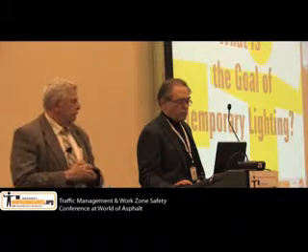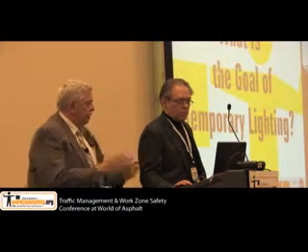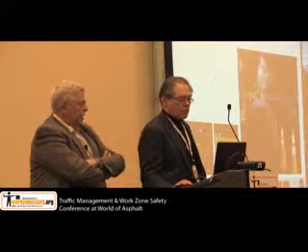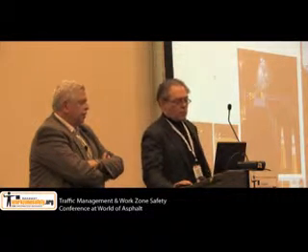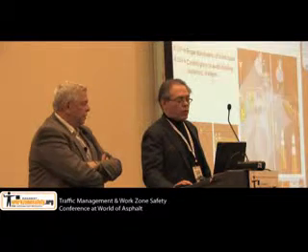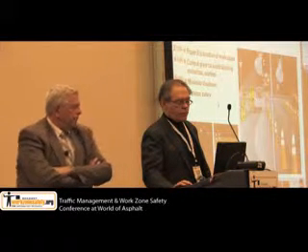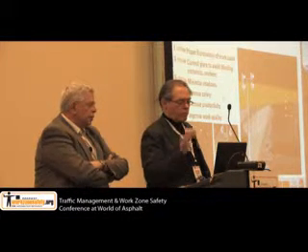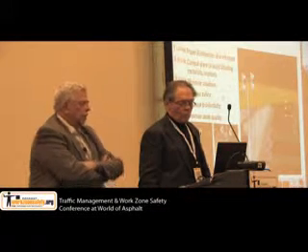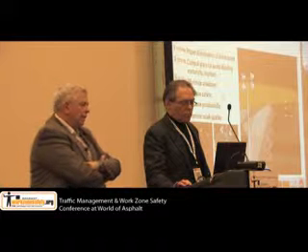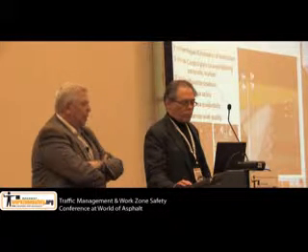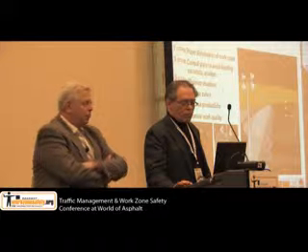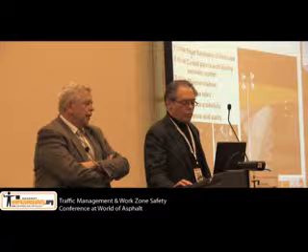And the goal that we have here of the temporary lighting is, obviously, to properly illuminate the workspace. You want to control glare to avoid blinding the motorists and workers. You want to minimize shadows. You want to increase safety and increase productivity and work quality. And we have a couple little demos here.